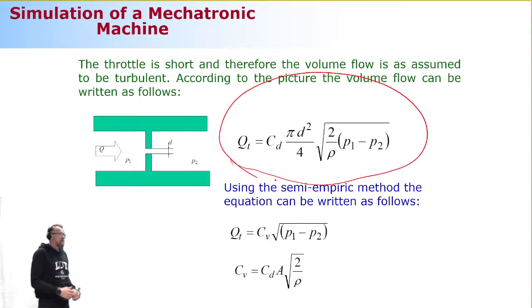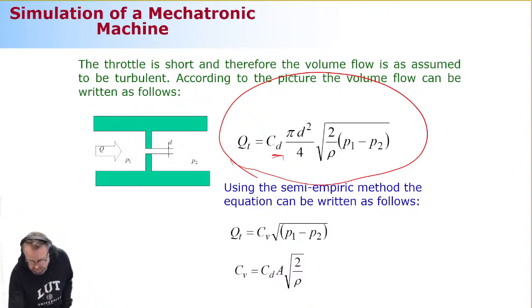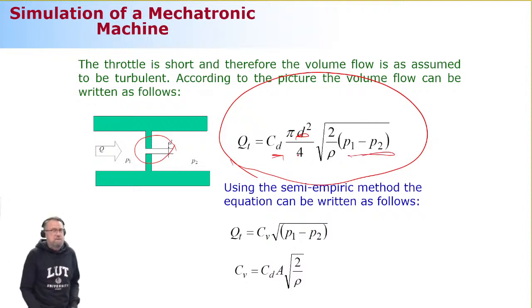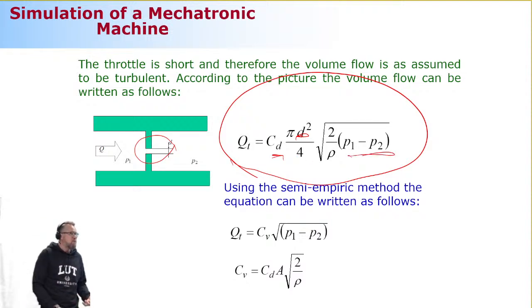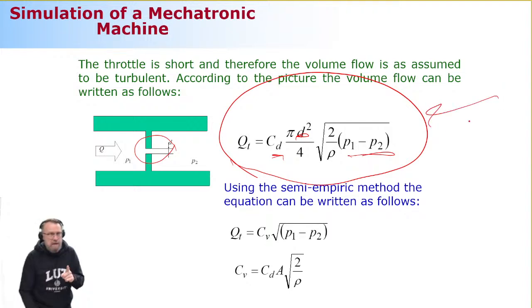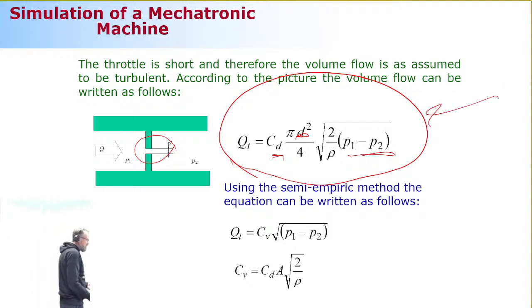It's going to be an equation that describes, first of all, the discharge coefficient. Those of you who have studied hydraulics know it: how much it is resisting the flow, or how much it is introducing pressure differences. Then there's the physical diameter of the throttle itself, then the density of the fluid, and under the square root is the pressure difference. So the pressure difference is under the square root, which means the flow rate and the pressure difference are quadratically related. The assumption I'm using here is turbulent flow. So you can model this as shown in this equation, explaining everything analytically, which is okay, but